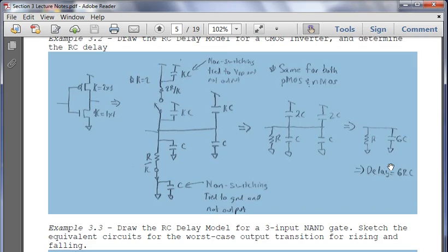And because that PMOS is switched, that's when it's going to contribute. Since that's the worst case scenario, that capacitance is going to be higher, and that's when we deal with that switch. So here, either one resistor or the other is switched on. Since 2R over 2 happens to be the same as R over 1, that makes it easy to calculate.